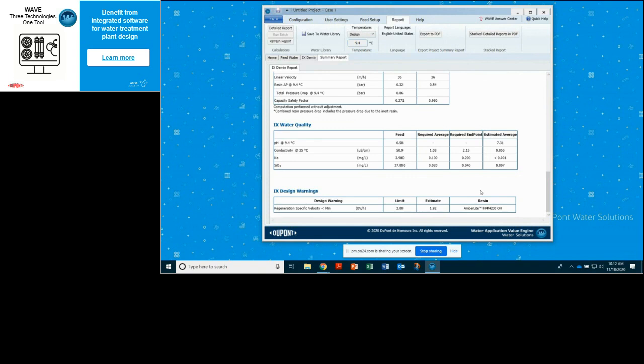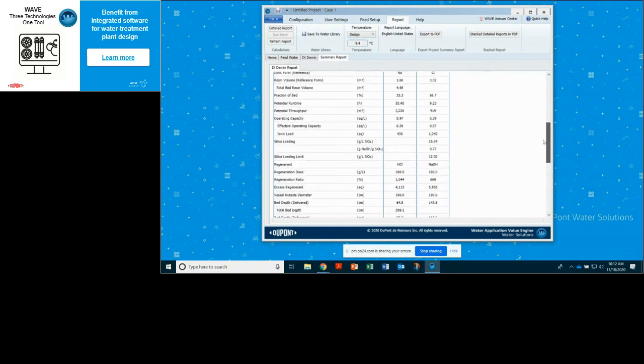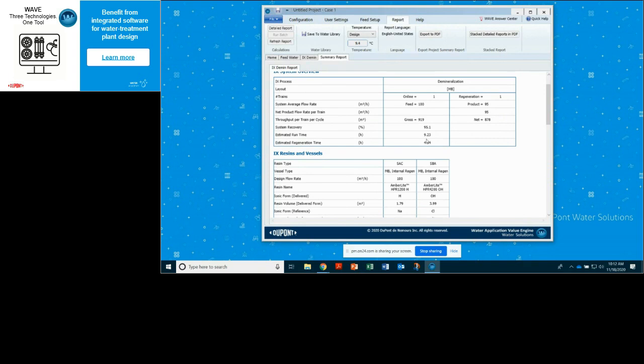That's come in a couple times actually through Q&A. Sure, no problem. So typically for a working mixed bed to be economical, the feed water is usually around 100 ppm or less. If we scroll back up to the top of the report, we'll see that in this design, we had roughly a 9-hour, 15-minute run length with a 90 ppm TDS, and the regeneration time is 4.5 hours. So that's getting to be a pretty short run length, given how much time it takes to regenerate it.